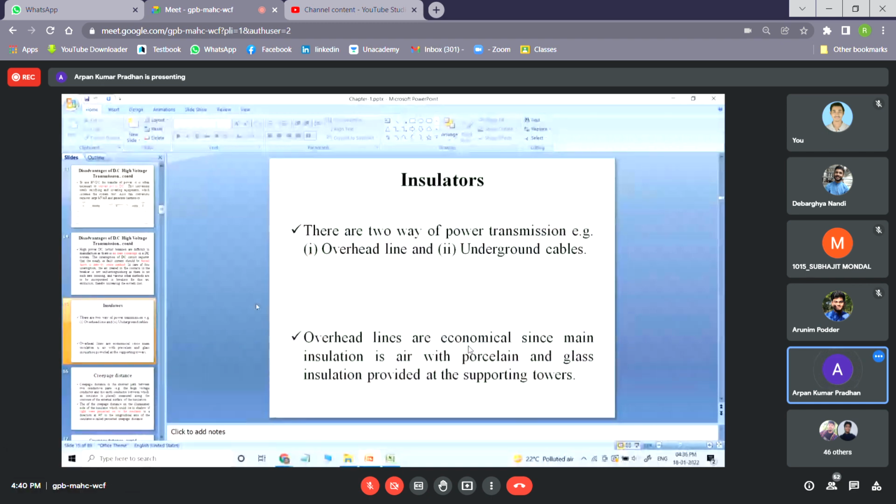But in case of DC, if you see the HVDC system, as the current is not crossing zero, it is quite difficult to operate the circuit breaker if any fault occurs. That's why you have to bring the current to zero, then you can operate the circuit breaker. That's why it is said that the current should come to zero, or the current is brought down to zero forcefully, then the circuit breaker operates. Is that clear?